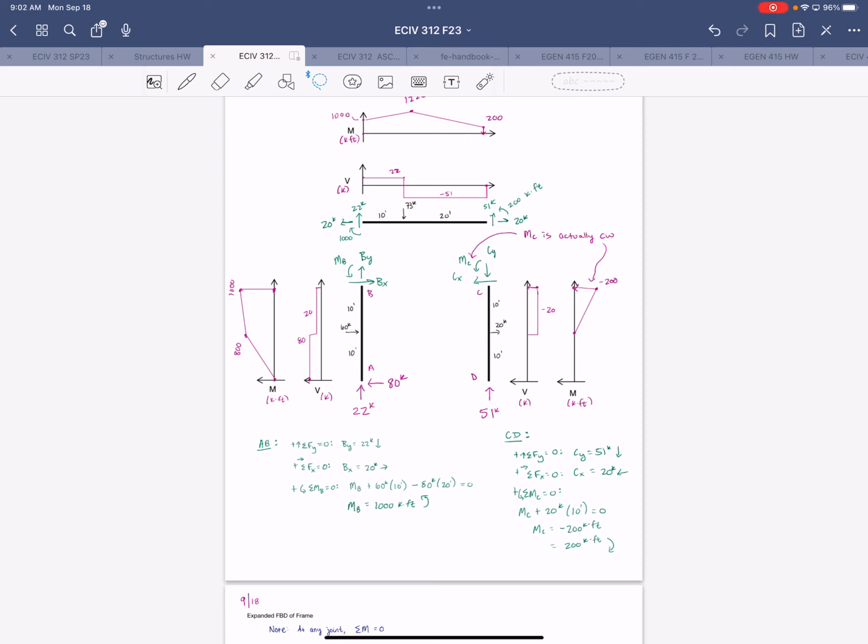we looked at a couple of those where, if all of the reaction lines intersect at a point, then it can't resist rotation. So you're ruling out instability flags, right? If you can do that, and you don't have anything else to think about, then it's totally fine to just say it's stable, it can't move without deformation, there are no red flags for instability, something along those lines. Yeah.